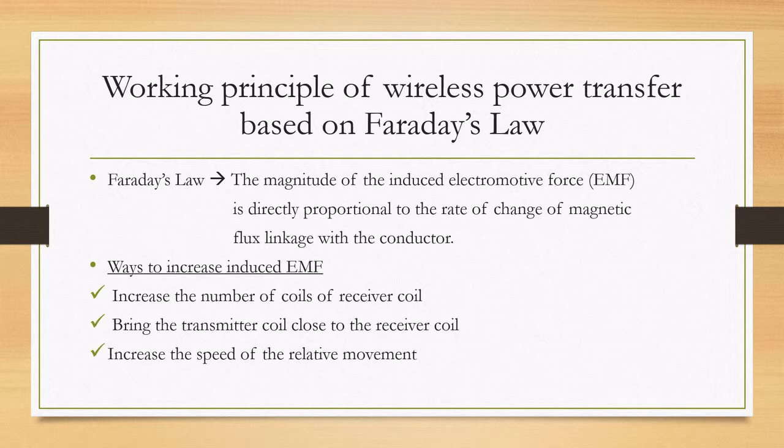The working principle of wireless power transfer can also be described based on Faraday's law. This is because Faraday's law states that the magnitude of the induced electromotive force (EMF) is directly proportional to the rate of change of magnetic flux linkage with the conductor. So, if we would like to increase the induced EMF, we have to increase the rate of change of magnetic flux linkage. Therefore, there are a few ways to increase the induced EMF.